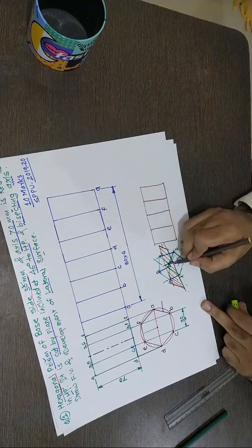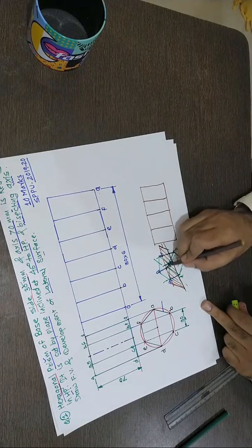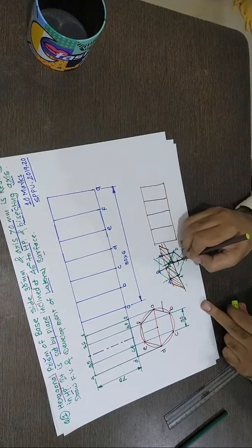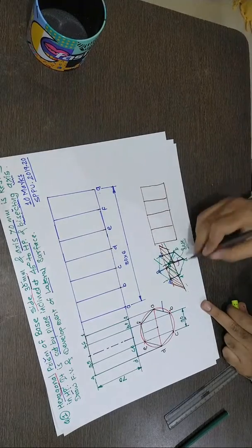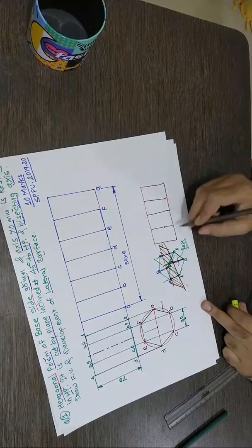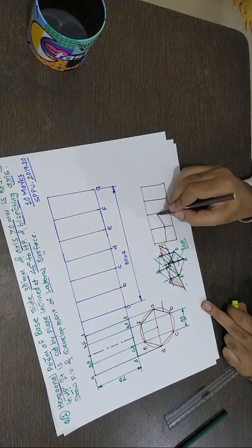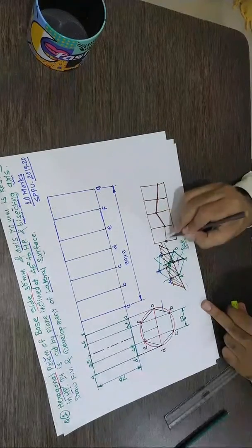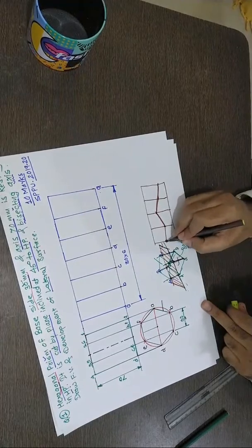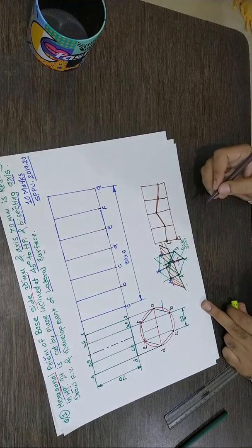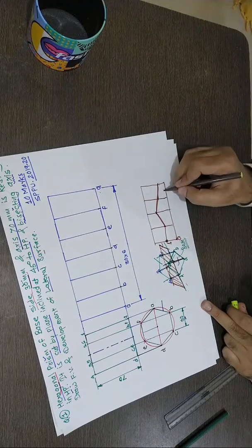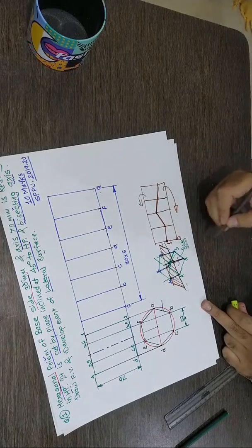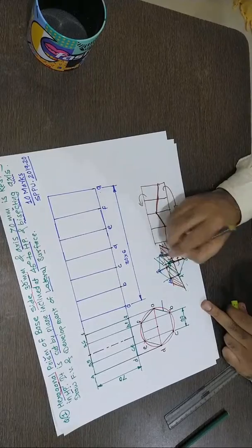When it is cut, this cutting plane will cut different edges of this prism, and this is, let's say, a height. So this height on one edge, we need to transfer somewhere on this development, on the respective edge. So it will be somewhere like this. Of course these are straight edges, not curves. Let's say this is A1, this is A, this is 1. So when I wind this shape again, clockwise or anti-clockwise, we should get the same surface below this plane and above this plane.